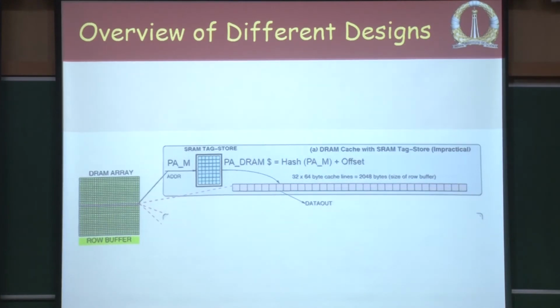If your cache had been an SRAM cache, you could potentially have accessed all of the tags in parallel, done tag comparisons and taken the data out of the multiplexer. But your cache is a DRAM cache. If I want to get the data from all these 32 ways, that might involve me getting the entire row, possibly from the row buffer, and then taking this out. This is a much larger thing, okay. So, you may not want to necessarily do that.